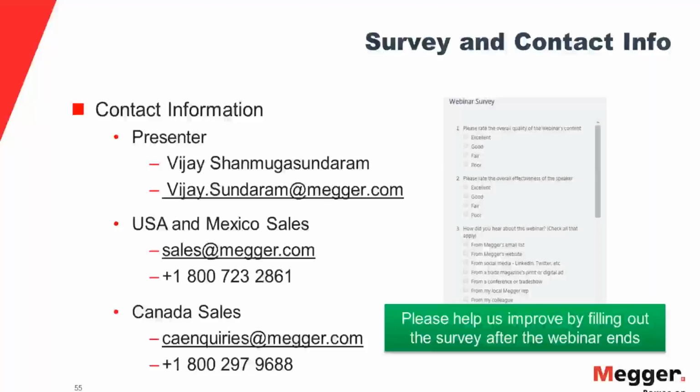Protecting your equipment is very important because any fault can damage the equipment permanently. So your differential function is a primary protection function for most of these equipments in your power system, or most of your assets. This differential function is highly selective and also sensitive. It operates for all the faults within the protected zone, and it restrains from operation, or it will not operate, for any faults outside of the protected zone.